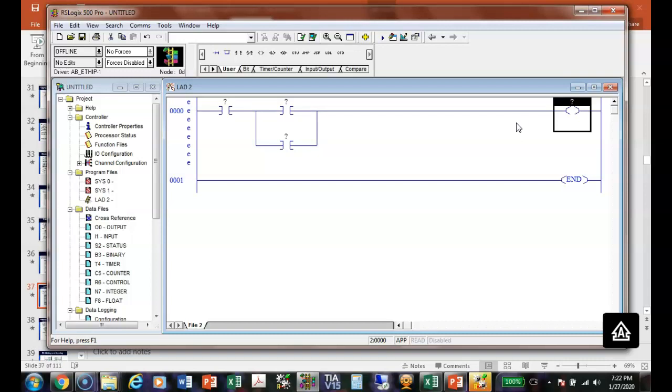This PLC, the RSLogix 500 series, this is a rack-mounted PLC. It's a modular PLC. The first thing in the rack is the power supply. The power supply has no addresses. Then in what we call slot 0, one thing you've got to learn in computers, everything starts with 0. So slot 0 is dedicated to the CPU. Slot 1 is dedicated to whatever you want to put in there.